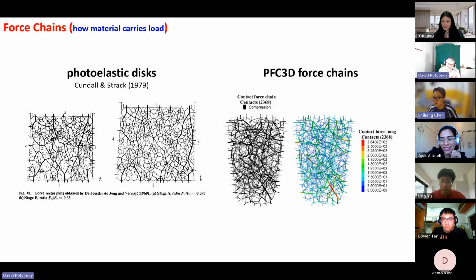I can just add a question here, maybe. So Yung King, the other thing you'll see a little later perhaps is, here's an example. Imagine this is a soil, okay? And we have a big building, but it's only 1/3 of the width of this box. And we now push down, okay? What you will see is a very high compression bulb here, but then there'll be almost no load out to the sides.